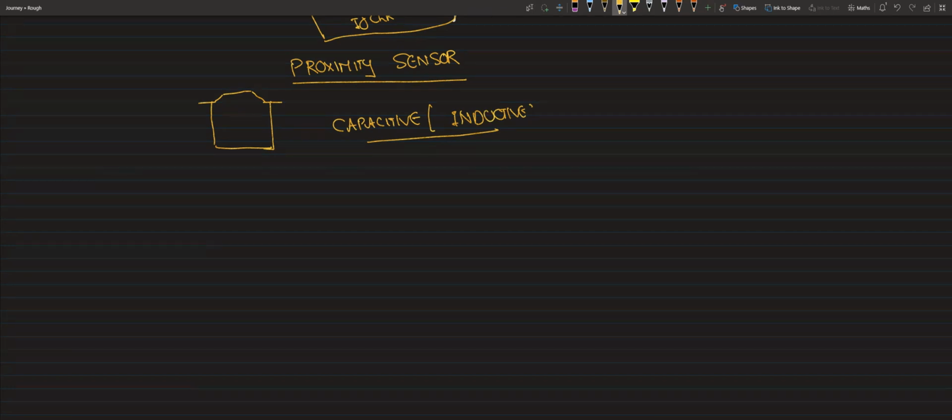Okay. Usually, especially when you want to control motors and so on, it will be very high voltage. There is always a possibility that you can spoil the microcontroller if that value exceeds a certain level. So for that, we usually go for something called optocoupling. Data from the sensor will be passed to the optocoupler whenever there is data, I mean, the proximity is reached.